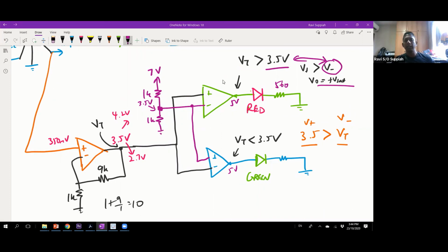Okay, so the LED itself, if you just connect it, it will still light up, but there's a high chance it will blow out very fast. Because if the current is too high, it will damage the LED. So you must always put a current limiting resistor to make sure you limit the current flow through the LED. That will ensure that the LED can still remain functional. If not, it will work for a while, then after a while it will just burn out very fast.